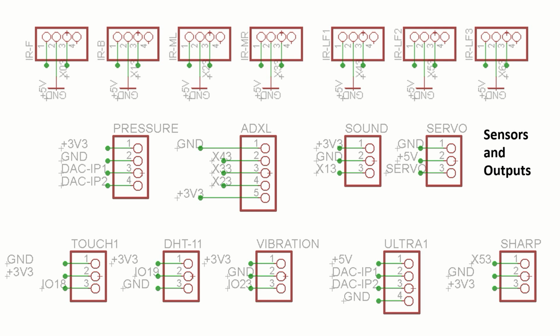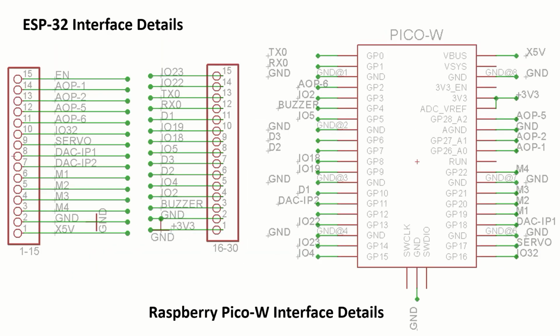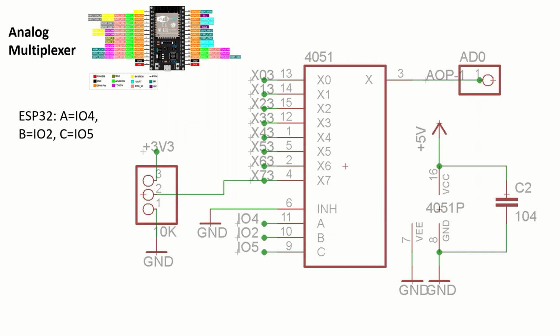So in total 7 sensors you can insert into these slots. Though I named them IR sensors, it is your choice. They could be analog or digital, because analog can also read digital sensors. Since there is an analog multiplexer, as explained in the first session, there are 8 inputs in total.